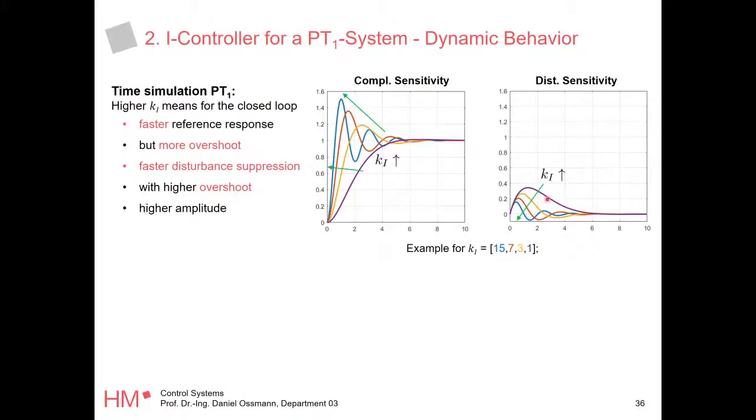The disturbance, remember when we had just a proportional controller, this went out flat here. This did not go to 0. For all the control gains, this guy gets to 0. So this is actually pretty nice. For our proportional system, we do get the control error down when we have disturbances, for all the control gains, whatever we take. And if we increase the gain, it gets better, but the oscillation gets a little bit bigger. So it gets faster, but you see the blue one is oscillating more than the yellow one or the magenta one, right? So you get more oscillations in.